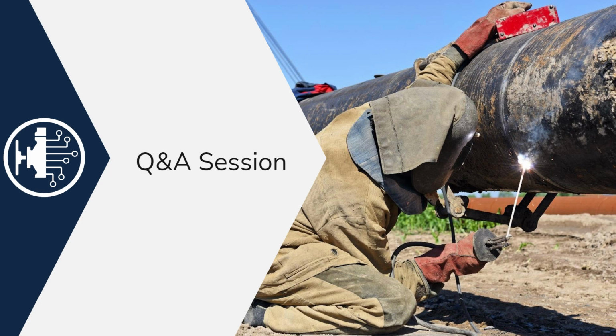Hopefully they don't design them so they use the ground as the negative. Unfortunately, we don't have controls over solar farms. We're hoping that they have a negative return on everything, and that it's properly set up so it doesn't leak current to the earth. But the problem is we don't know what's going on, because there are no rules or regulations on solar farms.